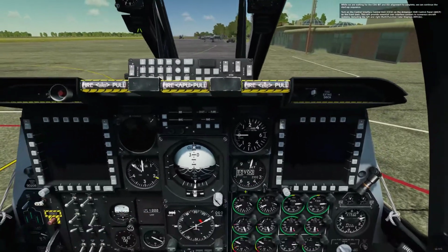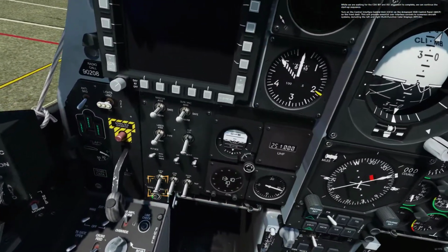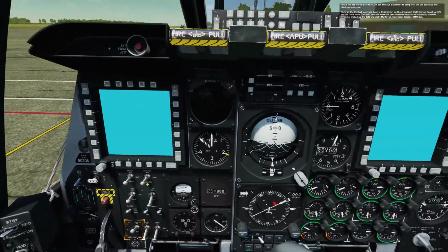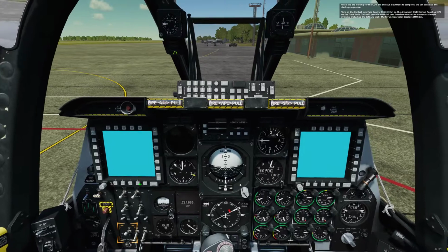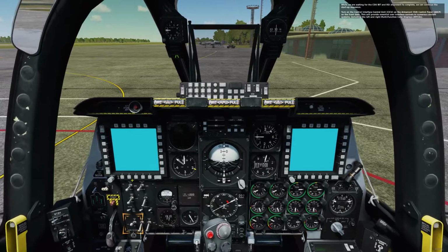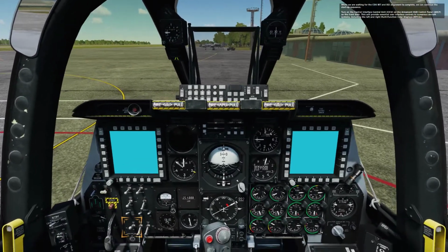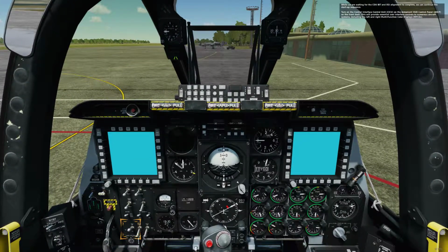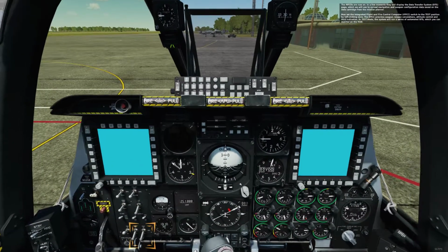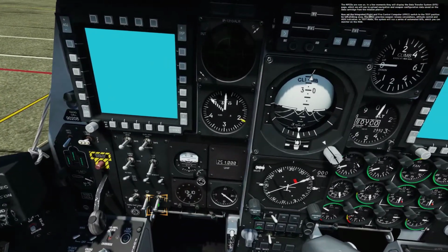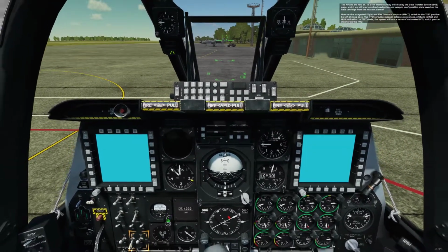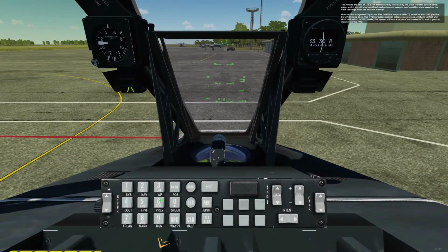While we are waiting for the CDU BIT and EGI alignment to complete, we can continue the startup sequence. Turn on the Central Interface Control Unit, CICU, on the Armament HUD Control Panel, AHCP, on the front dash. This will provide essential user interface controls to numerous aircraft systems, including the left and right multifunction color displays, MFCDs. The MFCDs are now on. In a few moments, they will display the Data Transfer System, DTS page, which we will use to upload navigation and weapon configuration data saved on the data cartridge from the mission planner.